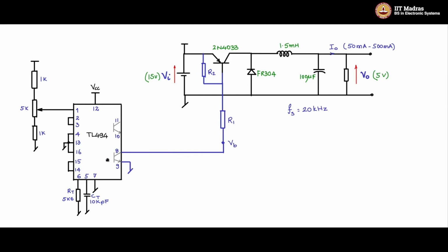Now let us say the internal enabling pulse is removed for the internal transistor. This is open. When this is open, pin 8 is floating. So there is no chance of current to flow through. Current IB on can't flow here. BJT is off. So in this way, BJT can be turned on or off by controlling the internal enabling pulse to the internal transistor of the TL494.